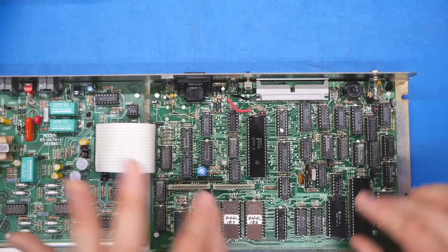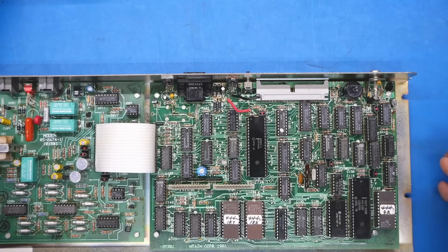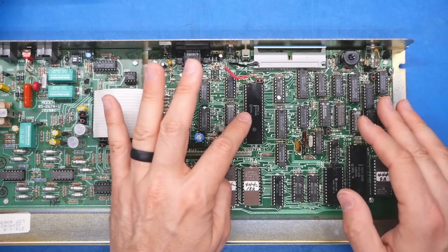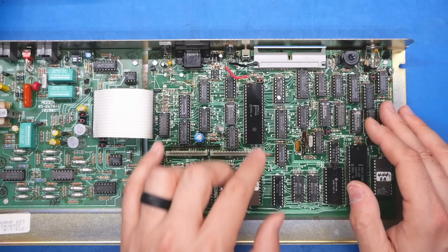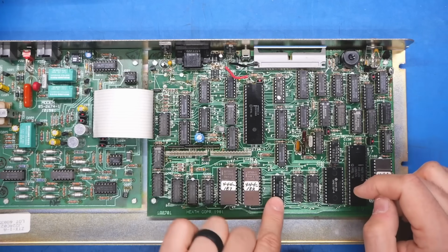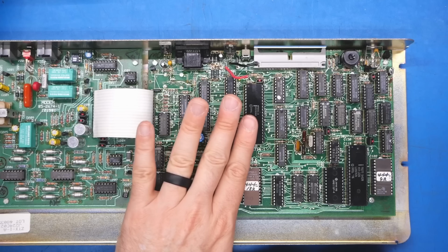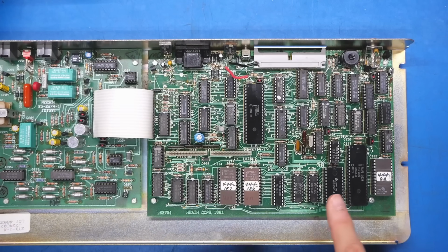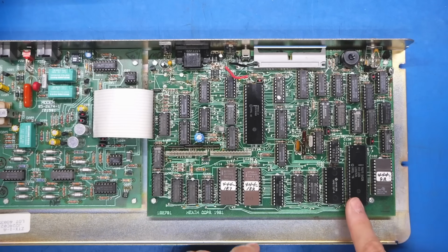I haven't figured out exactly which is doing what, but definitely it seems to be a split power rail for some reason. We also learned that from a data bus perspective, the CPU is directly connected to the ROM chips for the data bus, and this thing does not have any built-in ROM, but the 74LS245 bus transceiver is separating the data bus from the CPU and the ROMs from the video RAM, this static RAM, the 1K work RAM or whatever you want to call it, and the CRT controller.